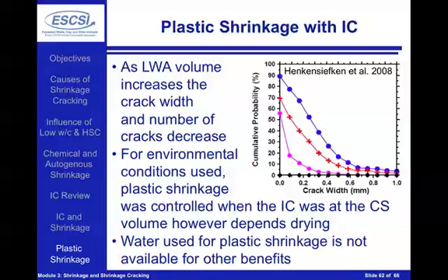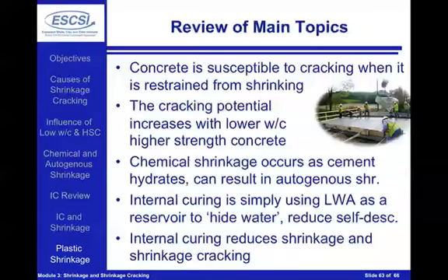It's very, very important to note here, though, that if we're going to use the lightweight aggregate to help in the plastic shrinkage environment, that water is going to get used up and it's not going to be available for many of the other benefits that we're talking about, either in long-term shrinkage or increased hydration or other things that we'll talk about in Module 4.